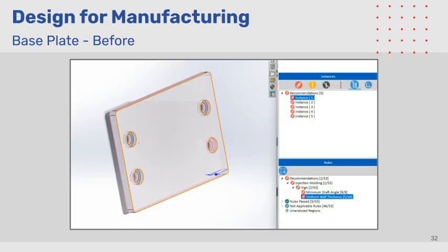The first part redesigned was the base plate, which serves as a surface protector, ensuring the metal base does not chip any countertops or tables the pasta maker is used on. As seen above, as per DfM Pro rules, there were issues regarding the uniform wall thickness as well as minimum draft angle when injection molding. The operating cost for this model is 2 cents. The mold cost is $1.72, given the production volume of 50,000. And the material cost is $2.50. The sum of these costs is the total cost of injection molding for this part, which is $4.24.